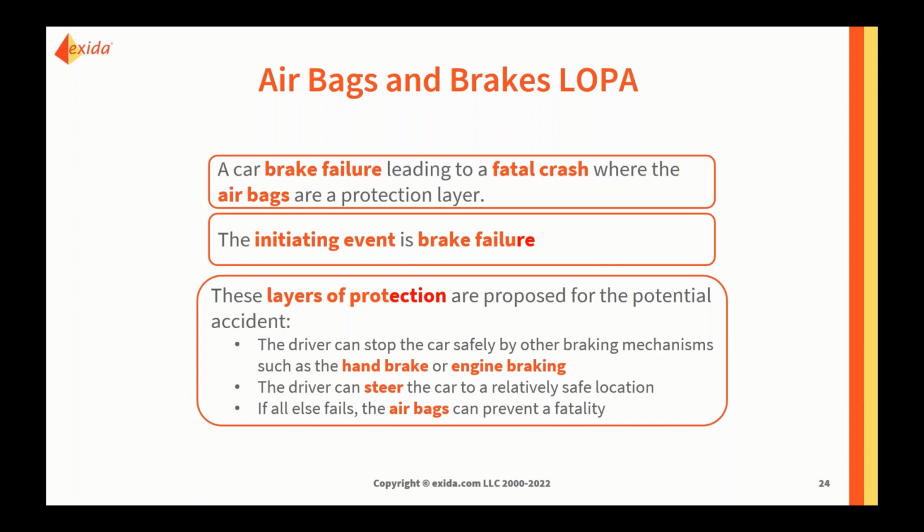And the first one is, I'll just call it driver action. The driver can potentially use the handbrake if the foot brake has failed, or can use engine braking to take the energy out of the car. The driver can also potentially steer the car to a safe location and avoid a fatal crash. But if our driver intervention fails, unfortunately, now we are looking at a crash, and the airbags come in to hopefully prevent that crash from being a fatal crash in all of this.